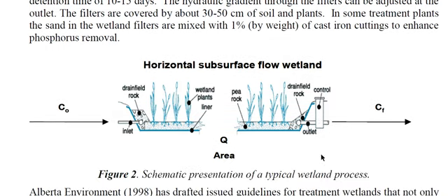And this is a drawing of a typical constructed wetland. And in these cases, we always use what is called subsurface flow wetland. Some wetlands, you just let the water flow on top, and they can be very efficient, but when there is a risk of spreading germs, spreading disease, you don't want that, because there can be kids getting in here or animals drinking and then spreading disease.